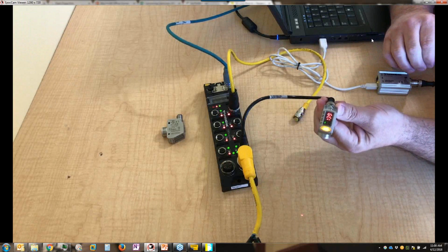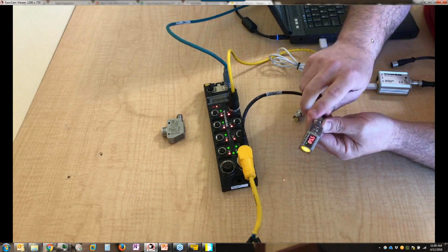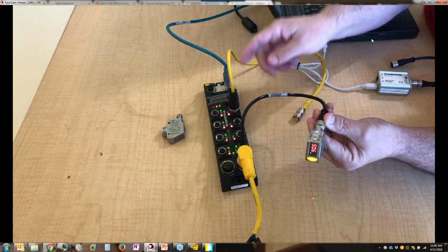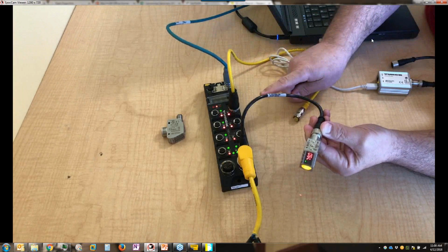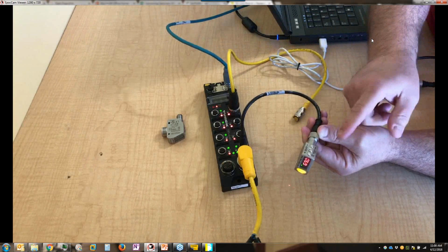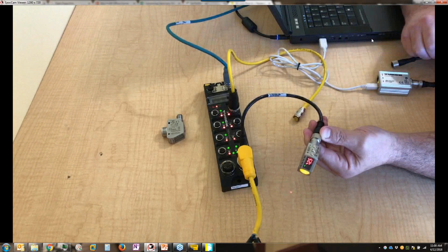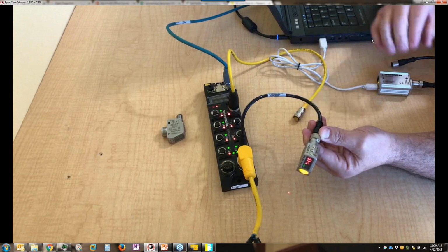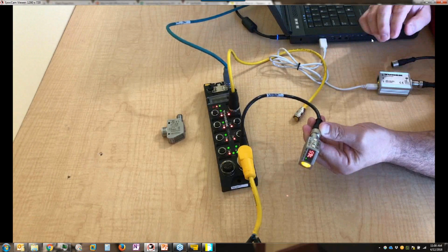I didn't have to go and dig out a data sheet. I didn't have to go back and reteach this smart sensor. Because of IO-Link and the parameter assignment server, just by changing one parameter on the master port, I can replace a failed smart sensor with another one, connect the cable, and just walk away, which is huge time savings when you want to get production back up and running. So that's that particular situation.